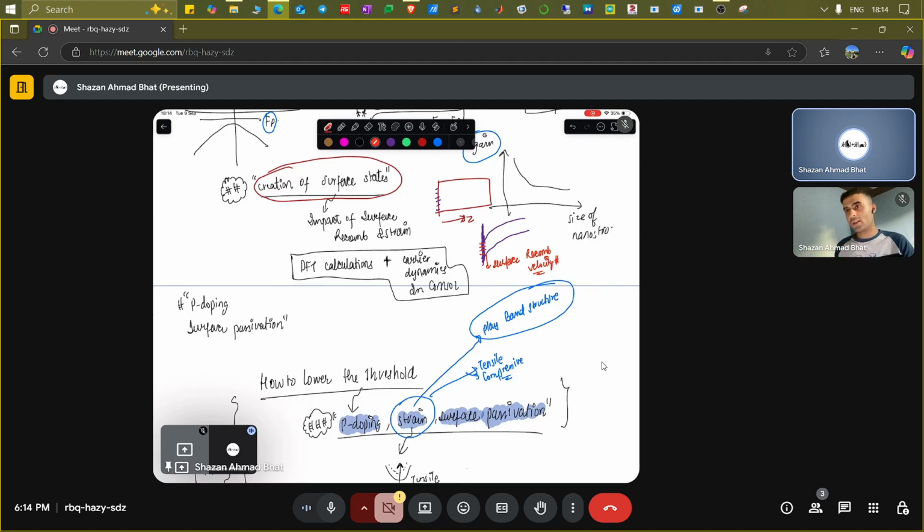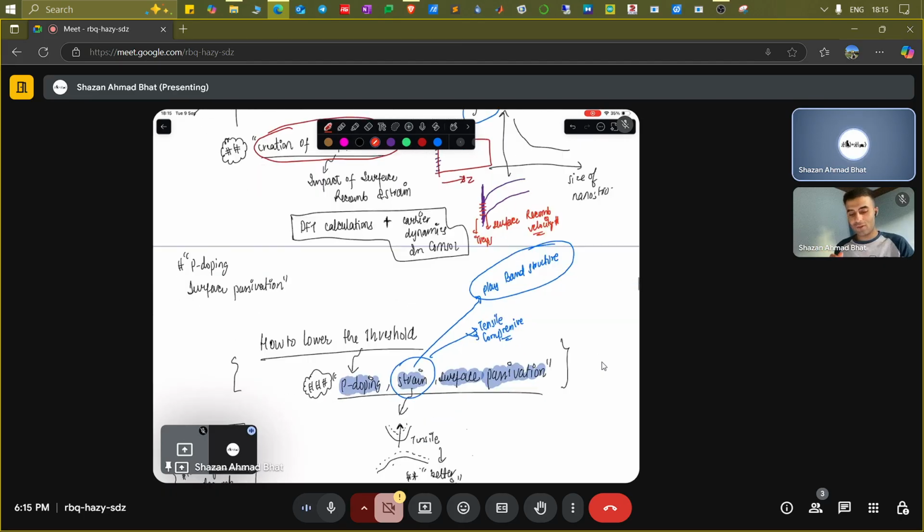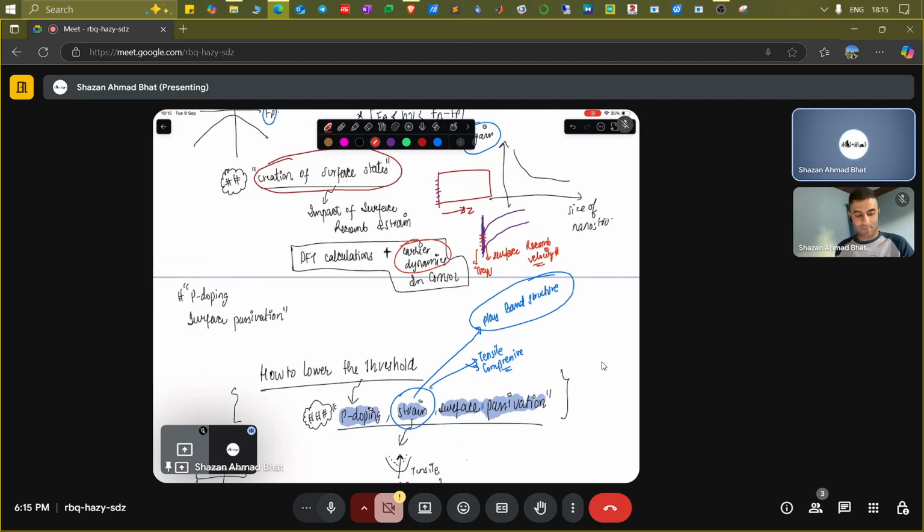It affects the motion of these electrons over the surface. So once that happens, because these are like traps, if an electron wants to move near the surface, it gets trapped and slowed down. And once they get slowed down, all of the responses change. This has huge implications in electronic devices as well. It impacts the mobility of the electrons, because wherever you find a trap, the electron gets trapped there and slowed down, and it has a huge implication in the carrier dynamics.